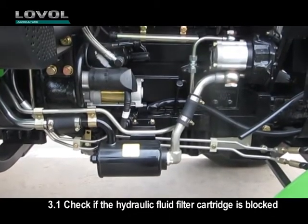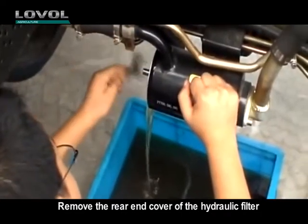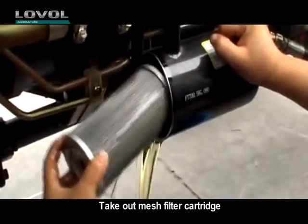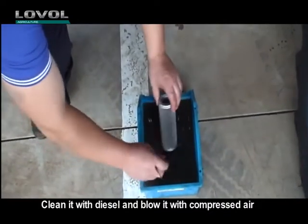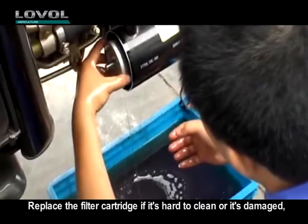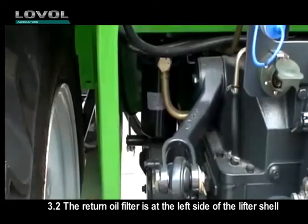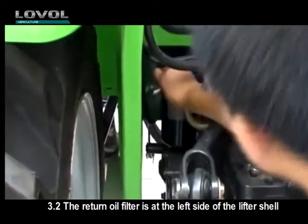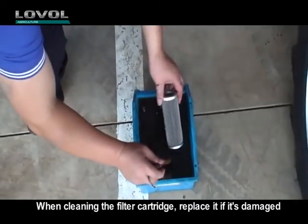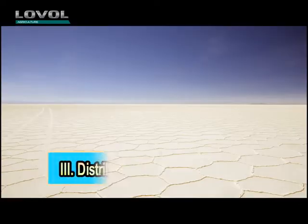3.1 Check if the hydraulic fluid filter cartridge is blocked. Remove the rear end cover of the hydraulic filter. Cap mesh filter cartridge. Clean it with diesel and blow it with compressed air. Replace the filter cartridge if it's hard to clean or it's damaged. 3.2 The return oil filter is at the left side of the lifter shell. When cleaning the filter cartridge, replace it if it's damaged.